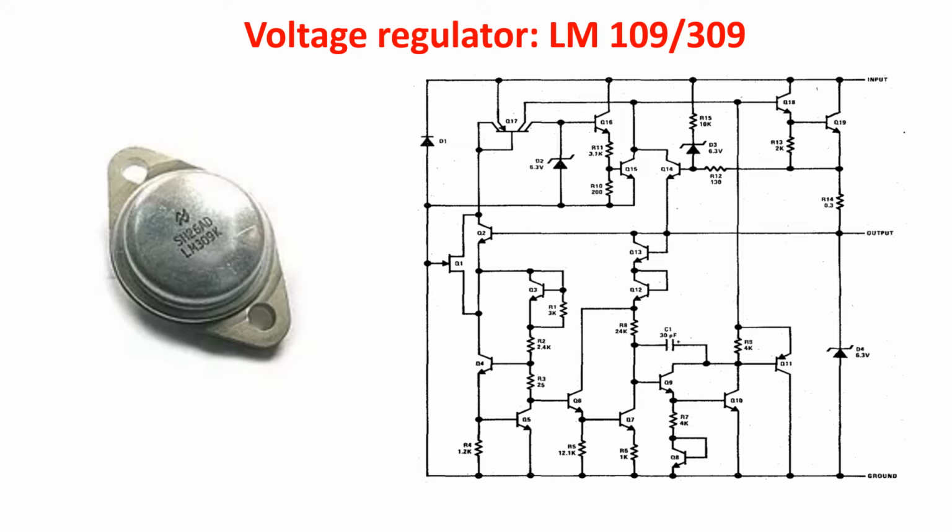Considering the temporal proximity of the two papers, some say it was a joke, or most likely, Widlar wrote against the case of the integrated pass transistor just to discourage competitors from doing so. In any case, he was the first to make the high dissipation of the pass transistor and the regulator circuitry coexist, introducing thermal protection alongside the bandgap reference.